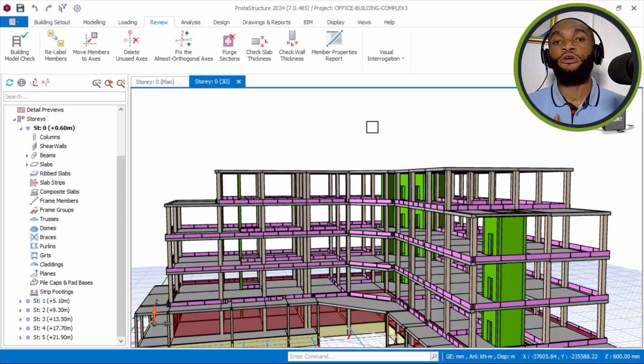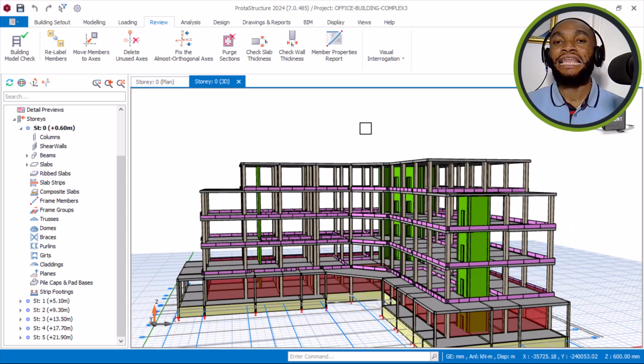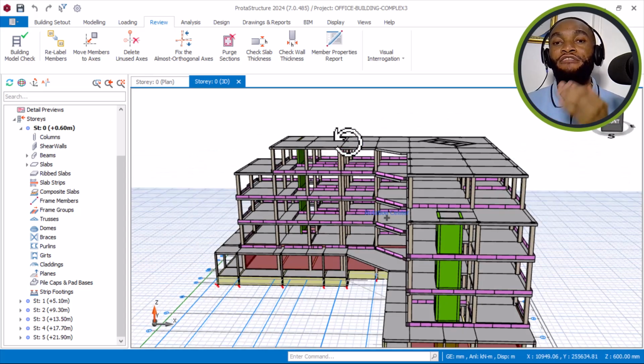But when you're using Google for your wind speed, you don't take the immediate wind speed to use for your design. You do at least what they call a forecast. You have to look at, for the past 5 years, what kind of wind effect has happened at that particular area where you want to erect that structure.